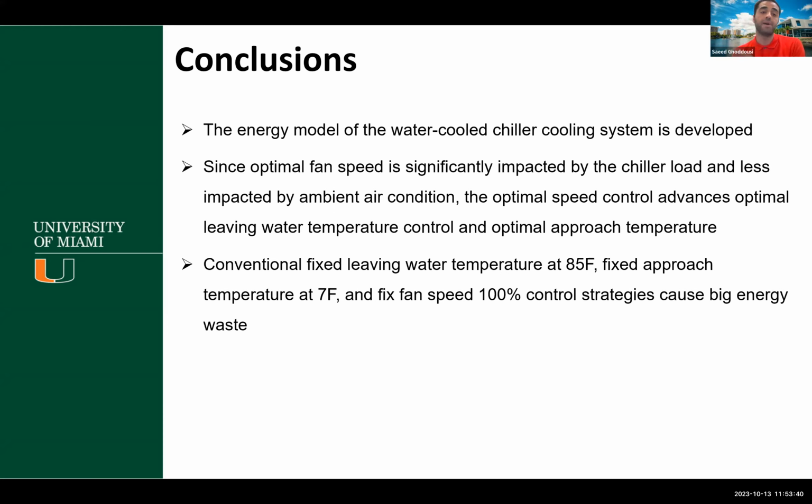We also evaluated the conventional control strategies: fixed leaving water temperature at 85, fixed approach temperature at 7 degrees, and fixed fan speed. We evaluated them by comparing to the optimal one to find the energy loss using these control strategies.